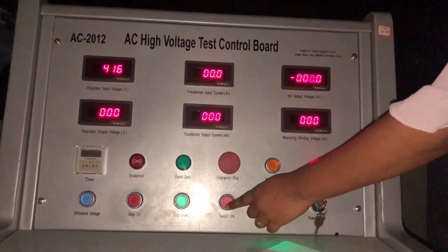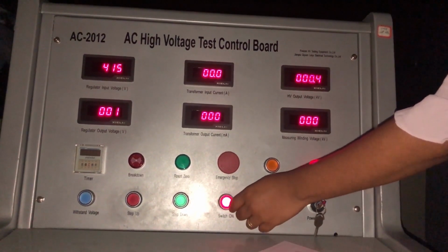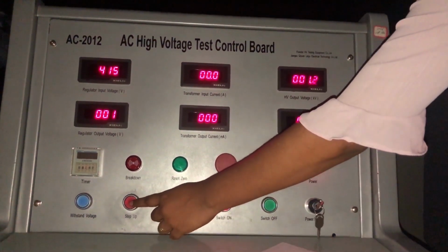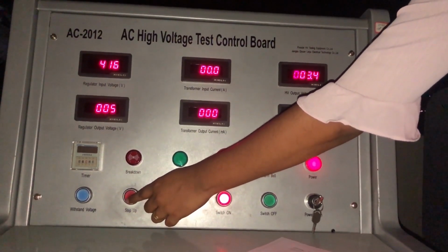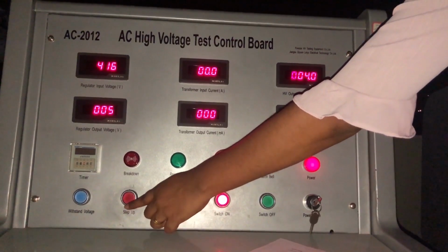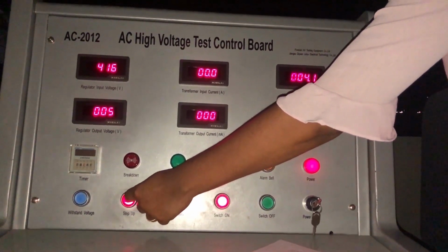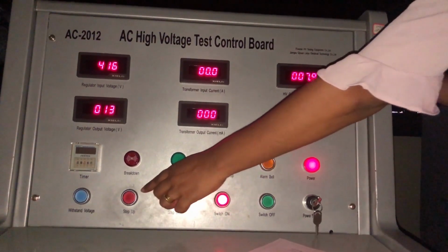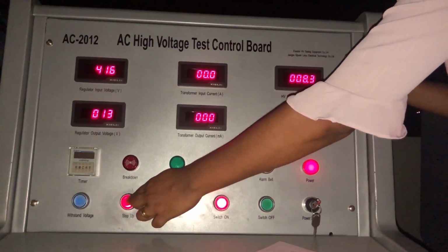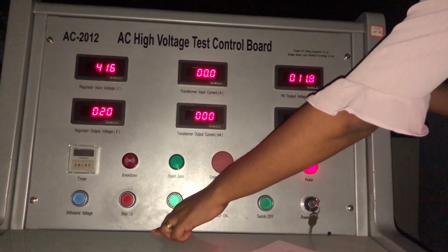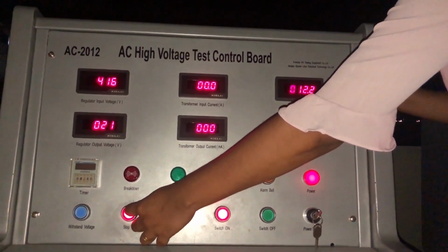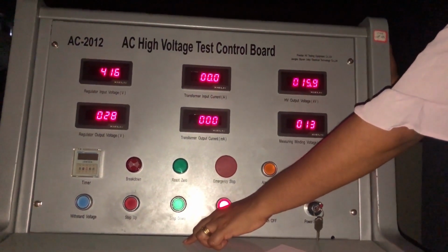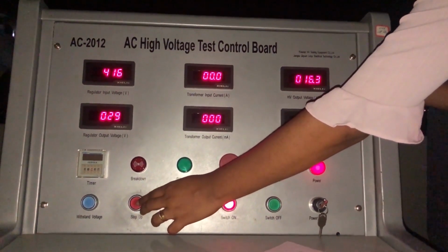After that, you have to increase the applied voltage gradually, using the step-up button, and observe the stages of the formation of corona, and you should record the respective voltages at which they occur. Make sure to wait for a moment after each increment. First, notice the disruptive voltage where you can hear the hissing noise. This value is equal to 21.1 kilovolts.